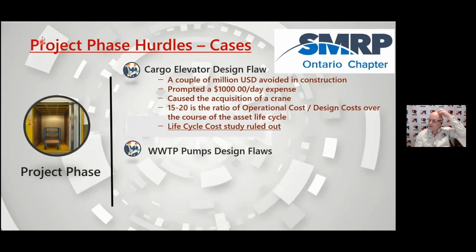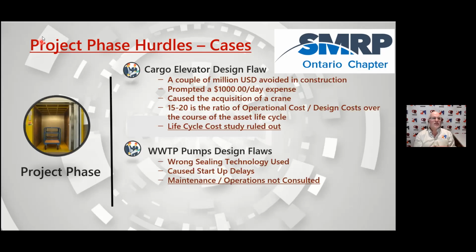Also, I remember another case, a wastewater treatment plant pump, with some design flaws, and the reason was very simple. The design team didn't ask for feedback from the floor people, from operation and maintenance people, on mechanical seals, and they installed the wrong seal.